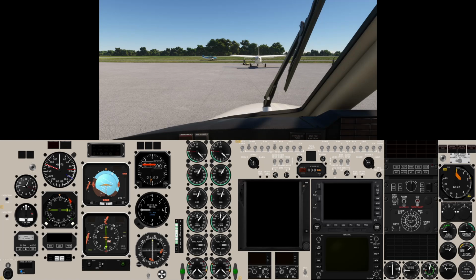And then in between the two annunciation panels, you've got a couple of autopilot panels. The top one is the mode selection, effectively, that you would see on any autopilot. You can see you've got heading, nav, indicated airspeed, VS modes, and all the other various bits and pieces. And below that, also part of the autopilot, are some other controls. Both of these have an annunciation strip running across the top of them, a little letterbox dark strip. You'll see when we get it powered up. There are annunciations on both of these, just to let you know what mode you're in.